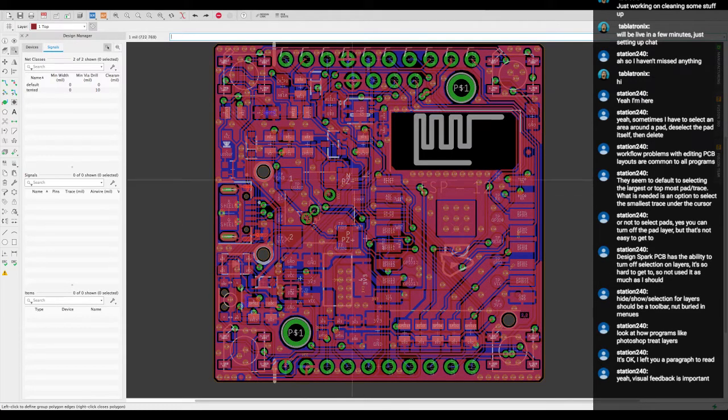So it was causing clicking on my piezo if you had deep sleep enabled, so when it would wake up, or when you restarted it, or when you programmed it, it would go click, click, click, click. So I added a pull down resistor to the base of that transistor just to suppress that.